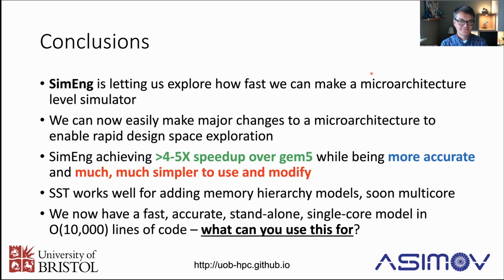There's stuff which is sort of generic across all architectures. For example, how large is the reorder buffer, or how many ports are there, and which units are behind which ports and such things. And I can see how it is easy to put that into a YAML file to make it configurable. But there are other things which are really specific. For example, in the A64FX, the presence of these two reservation stations, or another CPU, something that's really specific to the CPU, and that's probably not as easy to generically describe in a YAML file. So how do you handle this? No, that's absolutely right. So we think about this a lot.